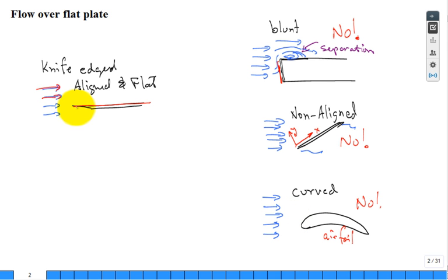So what does this do? It cuts it such that in this tip region, which is always difficult, always challenging, there's singularities there in fluid mechanics and in heat transfer, we get a nice mathematical expression by which we can solve for the fluid velocity anywhere over the top half of that knife-edged flat plate.